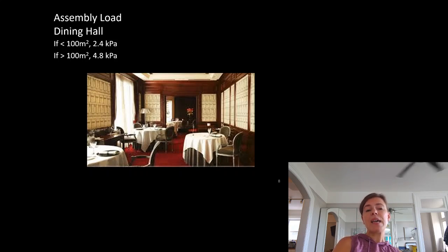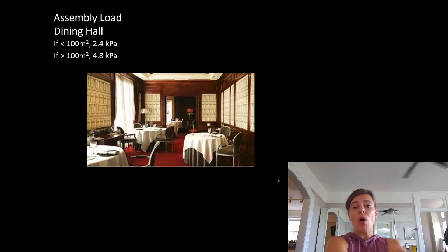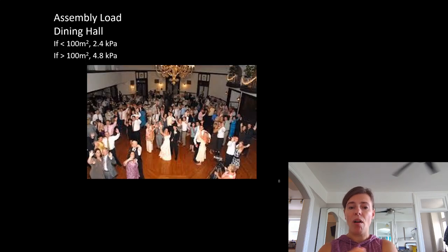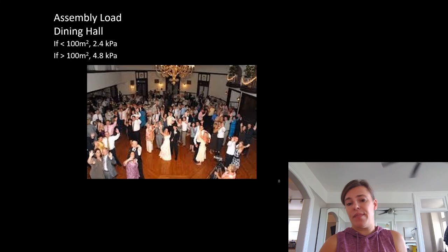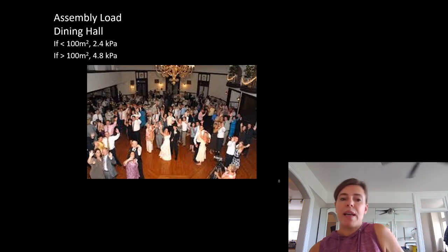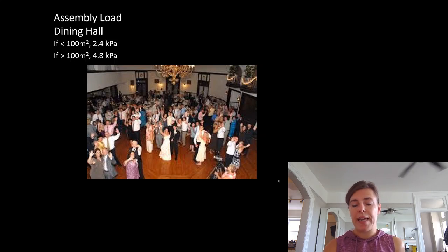Dining halls, if they're under 100 square meters, you can use 2.4 kPa. If it's over 100 square meters, you have to use 4.8 kPa. If anyone's been to a wedding where it serves as the dinner and dance area, you've probably been there where they say, go outside for a few minutes, come back, and that dining hall has turned into this. So that's why for a large dining hall that can have a big enough crowd, we have to assume that there probably will be dancing. Let there be dancing at the end of the night. And so for those, we definitely need to assume we could have 4.8 kPa.